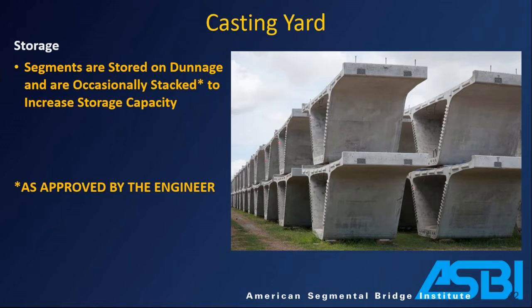And storage. You see a lot of pictures like this of segments cast in storage. Depending on the size and layout of the yard, you are going to need to store segments for a while. At a bare minimum, segments are usually 28 days old when they're erected. So a casting yard needs a lot of storage space. Some folks like to try to make best use of that storage by doing double stacking, and you can see the engineer in me is coming out here in bold text.